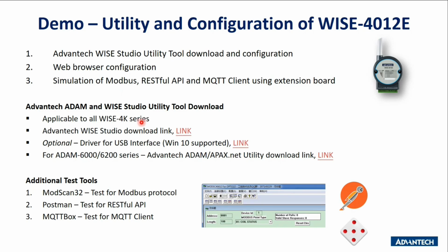right? So in this hands-on portion, I will use some test tools, some simulation tools, together. One of the software is ModScan. ModScan is mainly to pull the Modbus data, right? This is one of the test tool software. For RESTful, I will use Postman to query some of the status of the voice module, right? For MQTT, I will use MQTT Box to test the MQTT client.